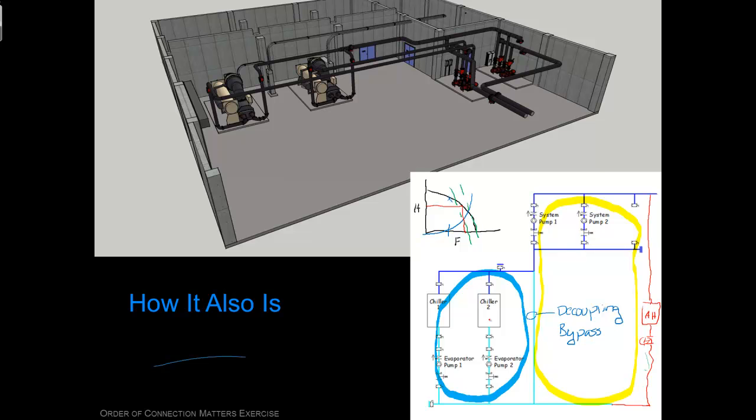So if the refrigerant got to 32 because of a proportional band or something like that in a proportional control system, you'd start building frost up on those tubes, which would restrict the flow, which would make a bad situation worse, and you could freeze the chiller up, which is a very serious thing, believe me. So in the olden days, with proportional controllers on the chiller, there's an error band. You couldn't flirt with varying the flow.